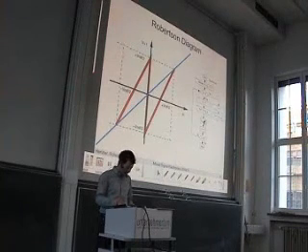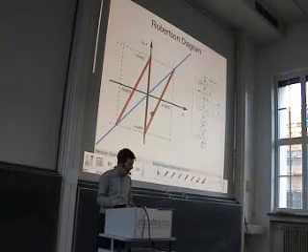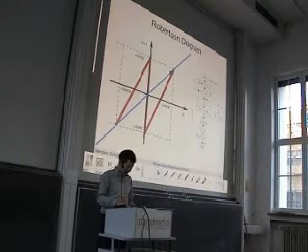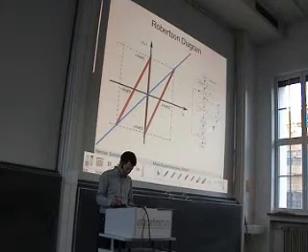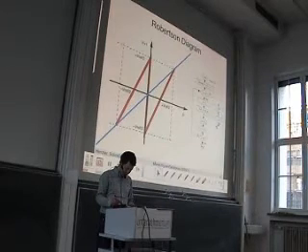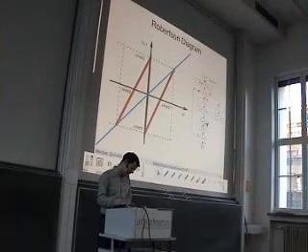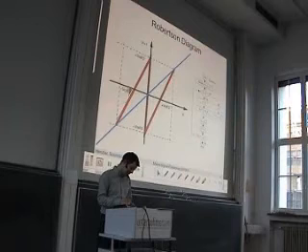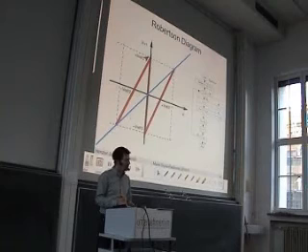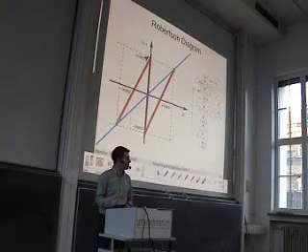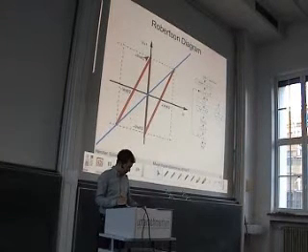And this gives us a new voltage that we use in the next iteration cycle given by this line. In the same way, if we are smaller than 0, then we increment the voltage and amplify the whole thing by a factor of 2, and this is described by this line. And the blue line was a help line for this graphical solution of the algorithm.